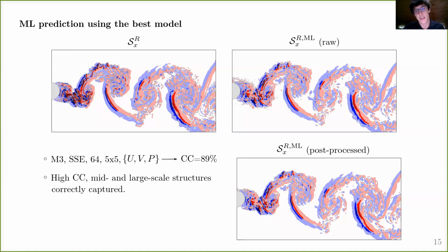So a way to mitigate this, not fully resolve it, is to post-process your machine learning outputs, applying some Gaussian filtering, getting rid of these high frequencies, and maybe also a wake mask, where the trivial regions of this wake, where there is an altered flow, wouldn't be predicted by the machine learning. So we try to stay focused within the non-trivial region, and we filter out the high frequencies. So this is how this post-processed machine learning prediction would look like in the bottom right.